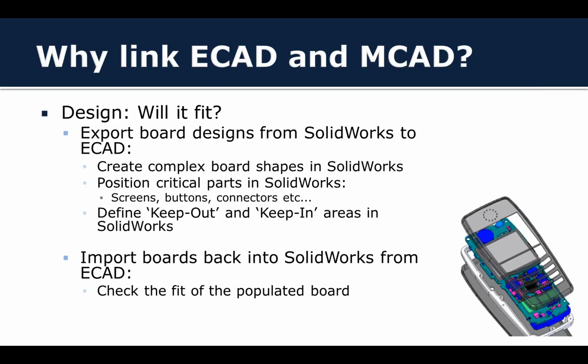Finally, people want to import boards back into SolidWorks from ECAD. A lot of people will actually create a DXF file, just a 2D shape, and export that information into your solid model and extrude it up to the board height. But we're proposing a different way of doing that, and that's what CircuitWorks will help us with.